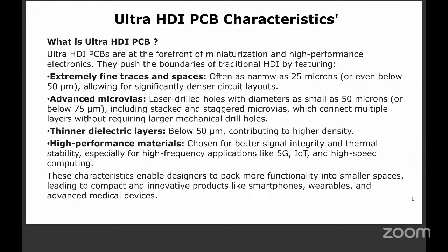And the usage of high performance material. People no longer use FR4. They use engineered materials. In fact, some of them are glass based and some of them are Teflon based. So these are the conditions for an Ultra HDI PCB.